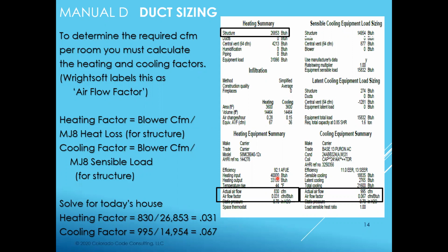That then gave us also this number here, this temperature rise. And I said that seemed a little high. You'd want to get more toward the middle of the temperature rise range. So I said we might want to increase this up another speed to get this number down. I think you see where I'm going with this.